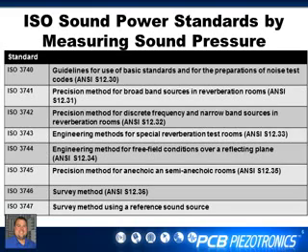A couple other standards that are involved in sound power measurements are the IEC 60651 sound level meter standards, as well as the IEC 61043 sound intensity standards, and I'll get to those at the end a little bit more. But for the most part, these are the guidelines to performing the methods, and most of the other standards with regards to sound power will be either specific to an apparatus or will outline the type of equipment or the type of analysis you do with it afterward.